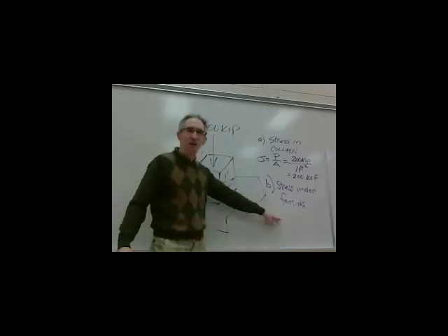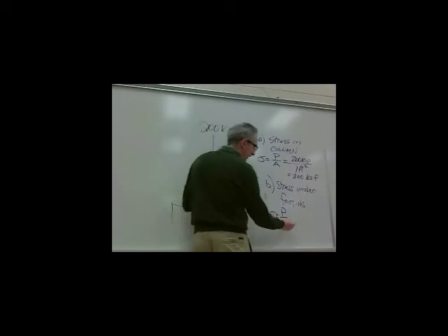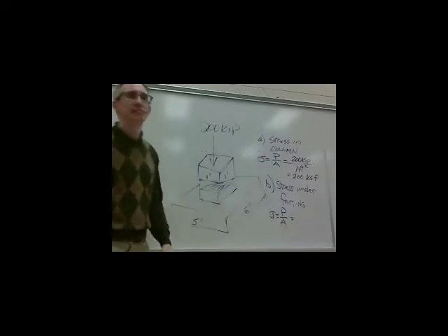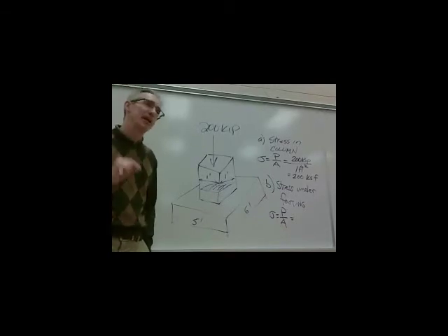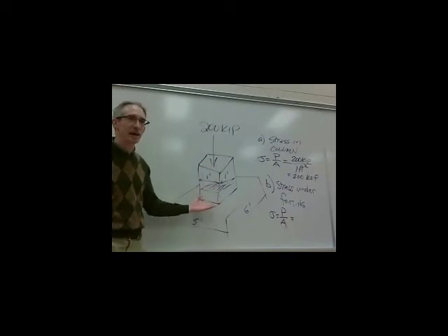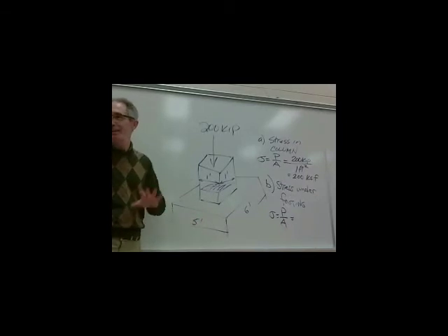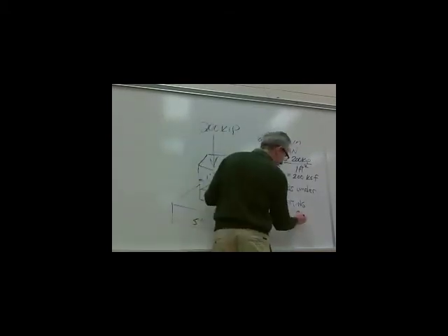What about the stress under the footing? Well, again, stress is equal to force over area. The force is what? The force is 200 kips. Now again, if you were really getting into this, you'd say, well, then there's the weight of the column, and then the weight of the footing, and so on and so forth. But we didn't say anything about weight, so we'll just neglect those. So we'll say 200 kips again.